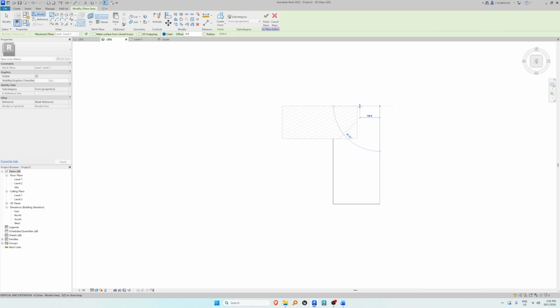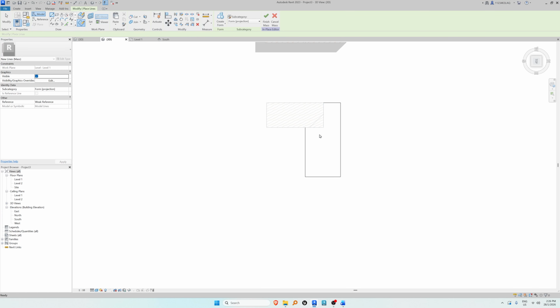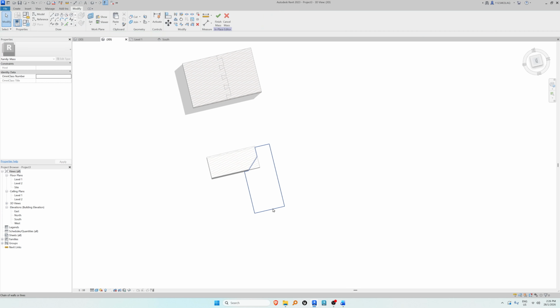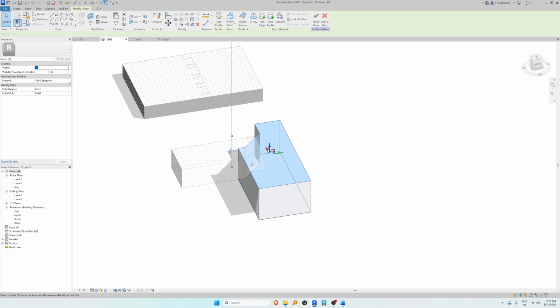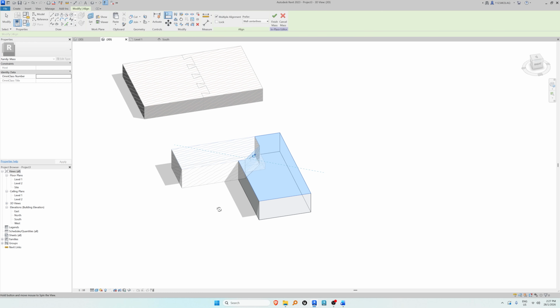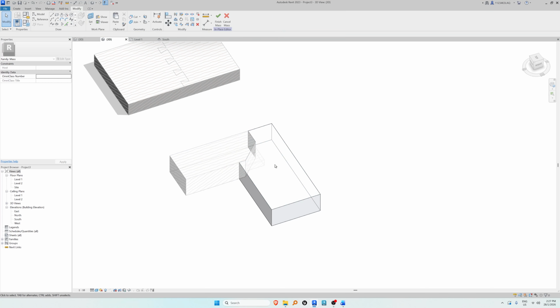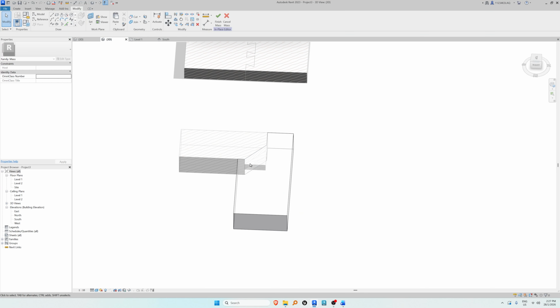Let's come to the end here, and then okay, let me cut this first. Right, let's do the full shape, because if we add the part instead of making a void, there'll be extra lines, so we don't want to have extra lines. Let's make a solid form, align this top to this one. Now we just have to cut out that part for the triangle in this one.